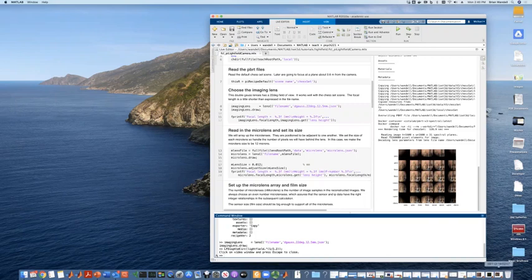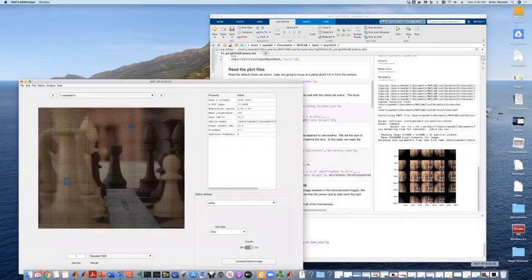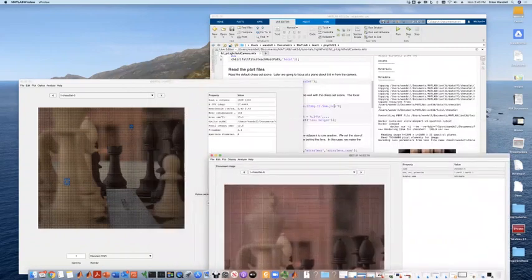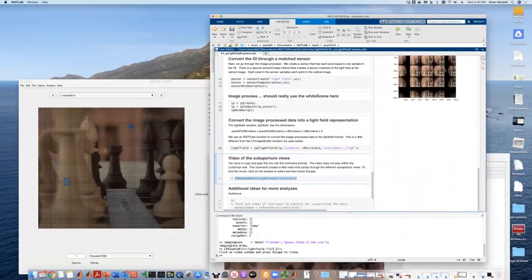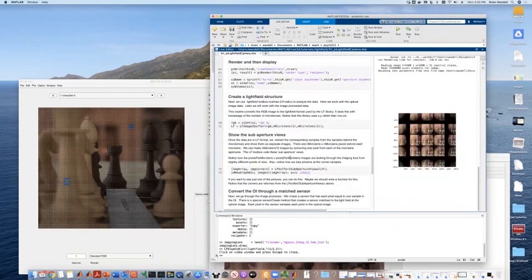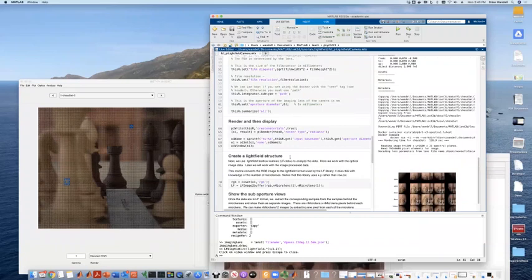And then that gave us the optical irradiance. It gave us the sensor image, and we then converted that into the image processed one as well. And so there are the data, and then we used Don Dansereau's toolkit to segment out the sub-aperture views and look at things from different points of view. All that's possible to do in simulation, and to try different sizes and different lenses and different demosaicing algorithms and so forth. And it's possible for anyone who has an interest in light field cameras and doing experiments with them. This is one way forward.